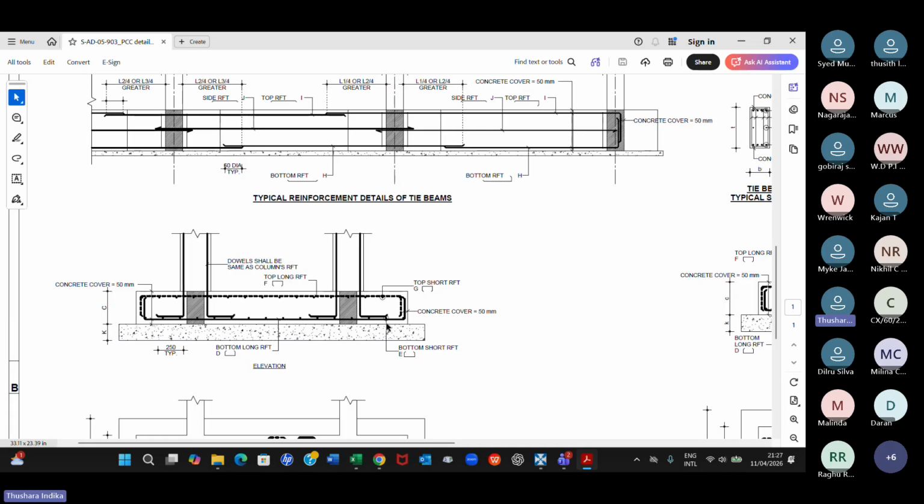Only this part, okay? Let's say we have not applied anything over here. So it is the top of the footings, side, and top or edge of the PCC, and maybe the sides of the edge of the PCC. That's all. And then beams, of course, tie beam sides. There are 2 sides and top. So those are the waterproofing areas. Okay, how can you derive these areas now from what we have measured already?